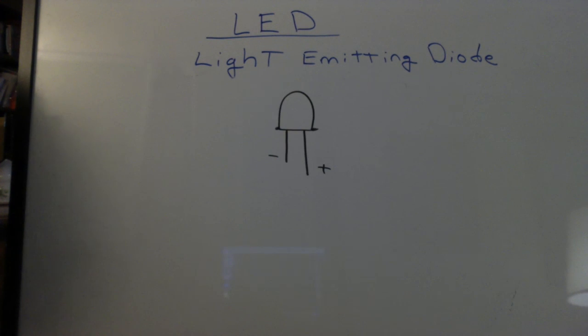This might be handy when we study magnetism and we have changing currents. So the LED should be connected with the long electrode to the positive side of the circuit. A reverse polarity can only be tolerated to a certain degree, just like the forward voltage can only be a certain amount before it burns out. So be careful how much voltage you use on these LEDs. If you burn any out, you can always order more online. They're not very expensive.